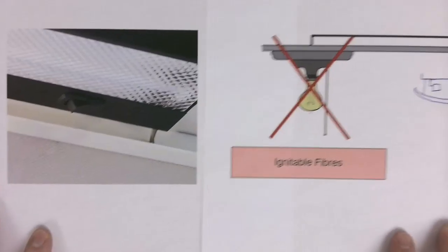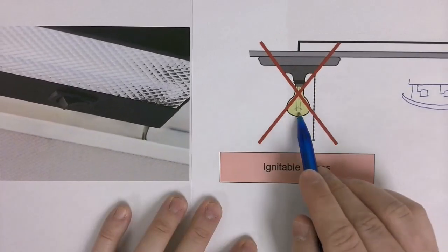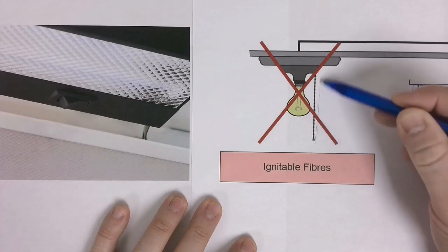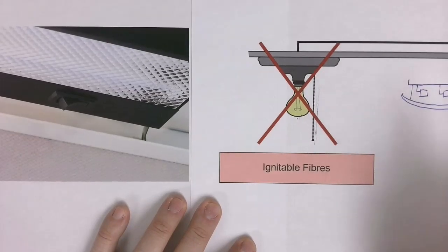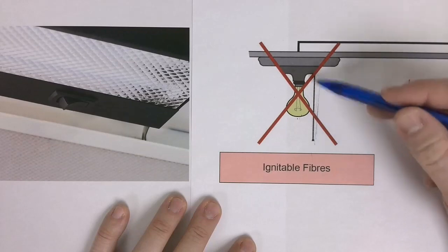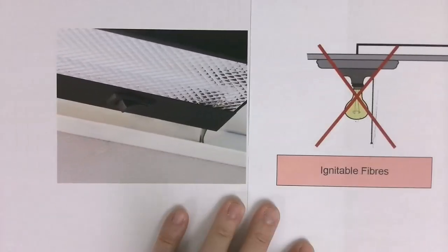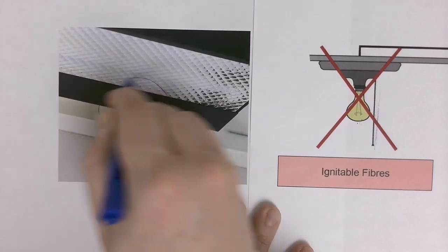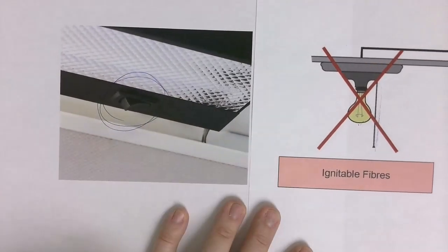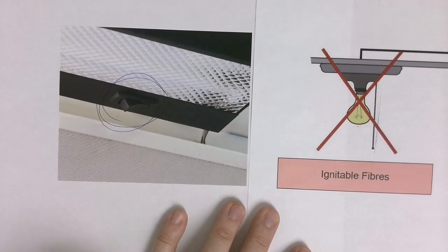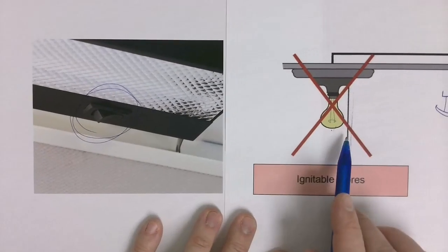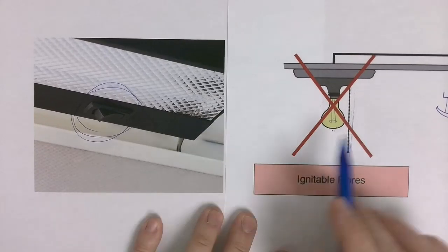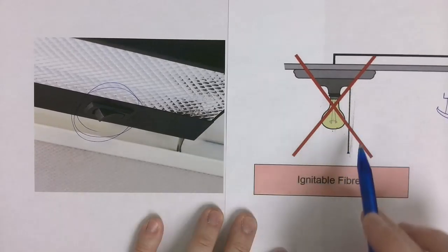Now, another reason we don't use this type of luminaire, which is usually called a pull chain lamp holder or pull chain light, because of this chain which acts as the switch. There's also these types of lights. Not sure if you can see that. There's a switch right here. Look at the pictures in your module. It might be easier to see. But these are luminaires with integral switches or built-in switches, sometimes called canopy switches.